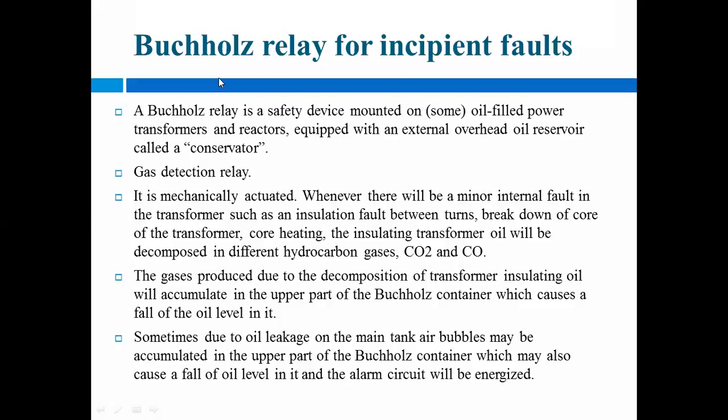The gases produced due to the decomposition of transformer insulating oil accumulate in the upper part of the Buchholz container, which causes a fall of the oil level in it.